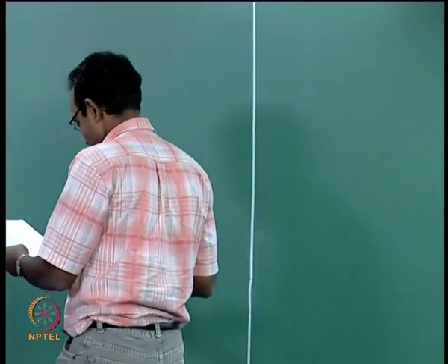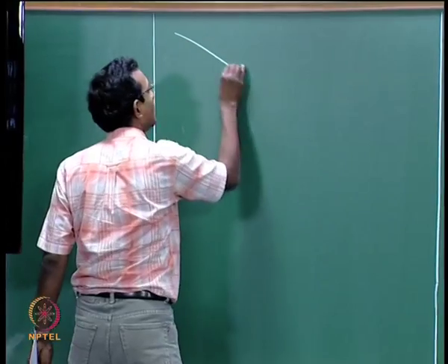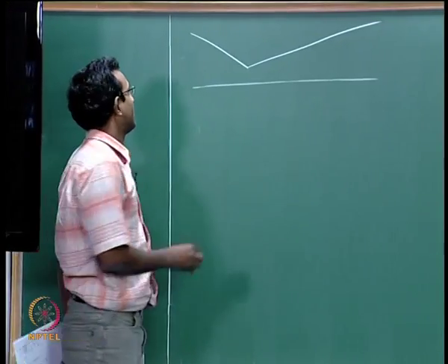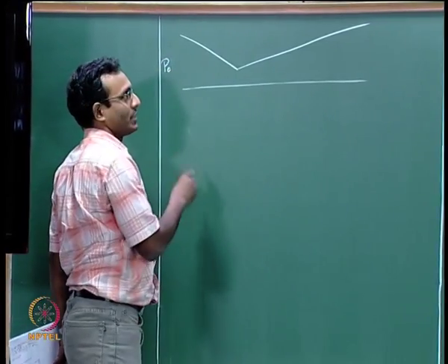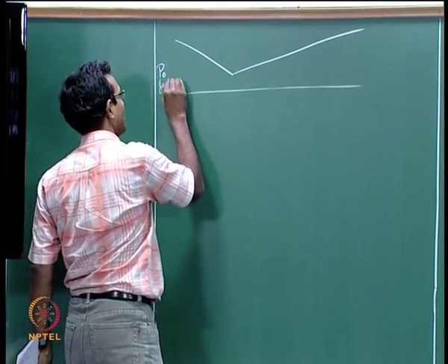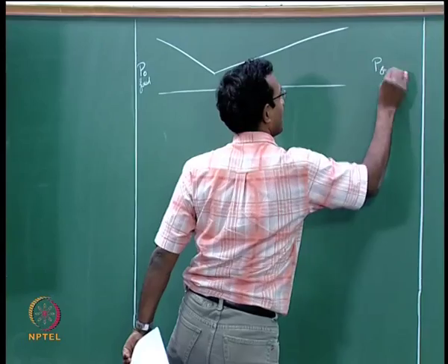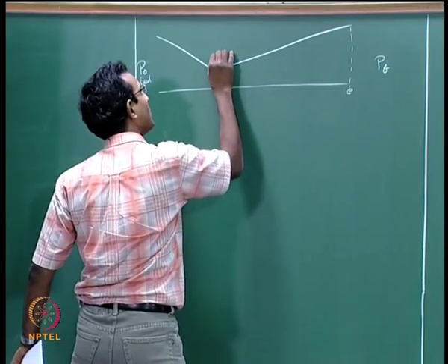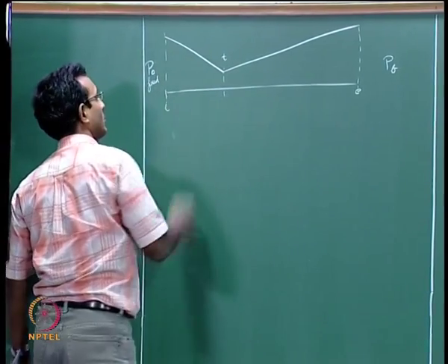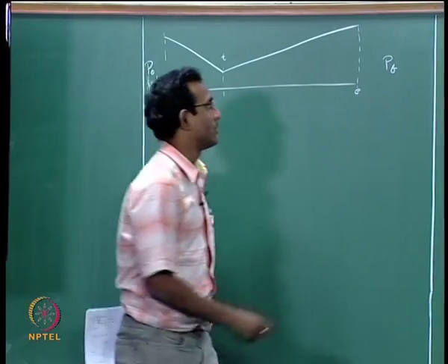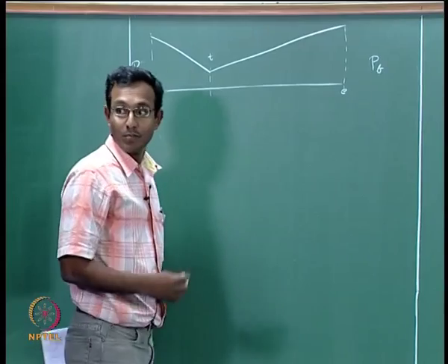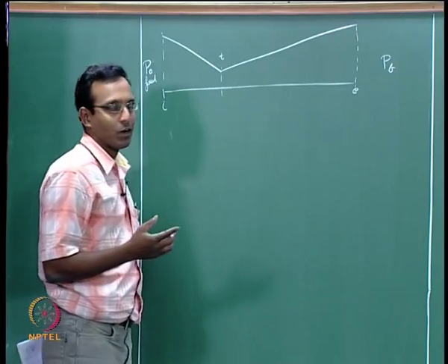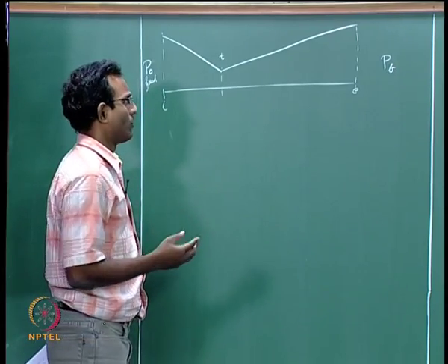Okay. We are having some convergent divergent duct, and we are saying that we are going to maintain P naught as a fixed value, and back pressure Pb is what we are going to change. We are going to slowly decrease the back pressure starting from equal to P naught value. When we start with Pb equal to P naught, we are going to have no flow.